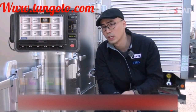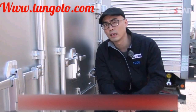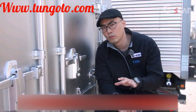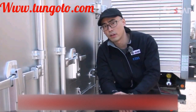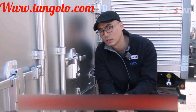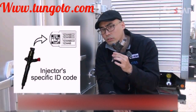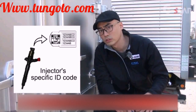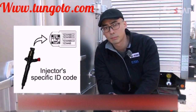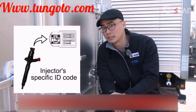Whenever you perform repairs on most recent systems, even simple replacement of sensors, you must use a scan tool to reset or erase learned data in the ECU. Other than erasing and learning function, there's calibration, initialization, reset, and coding functions. One out of many different examples would be injectors. When you replace injectors, you have to code or write the specific injector's ID code into the ECU for correct fuel quantity adjustment.